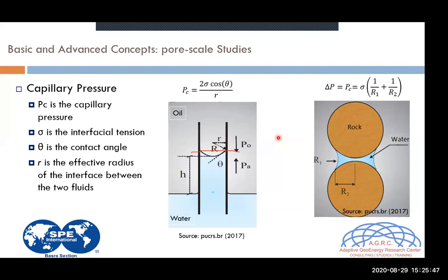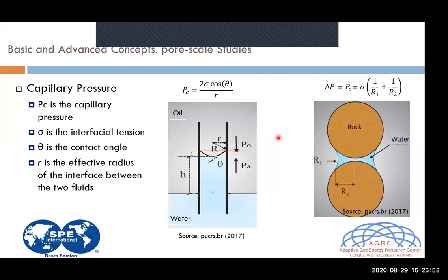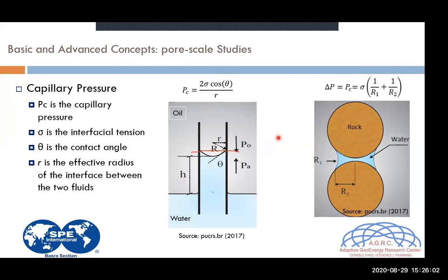And if, for example, we have high salinity water, and then we start injecting fresh water, this will affect the interfacial tension of the rocks, and the wettability will be changed.